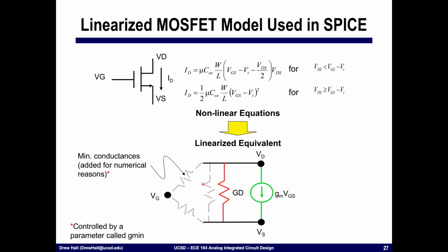Okay? So normally, this is not a problem. I don't really care if I have a 1 gigaohm impedance between multiple nodes in my circuit. However, there are times when you are designing circuits that are either very, very low power, or have impedances themselves that are comparable to this, in which case we need to know to go in and change this parameter and increase the tolerance. Okay? What's the impact of doing this? Well, it essentially makes the simulation harder. SPICE has to work harder in order to find the operating point because it can't condition the matrix quite as effectively.